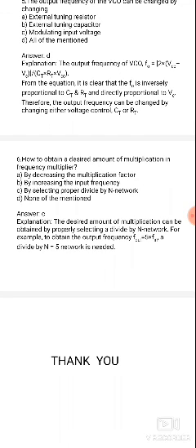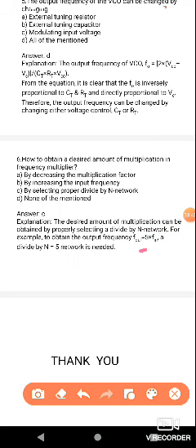For example, the output frequency f out is a multiple of fn, or the multiple is nothing but a harmonic of fn. Here the multiple is phi into fn, so a divide by n network equal to phi is needed. Here we can get n is equal to phi.